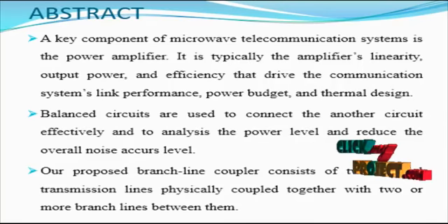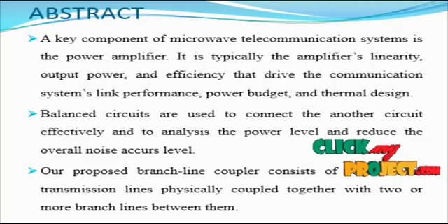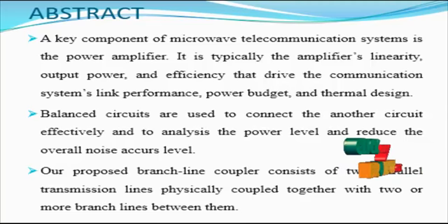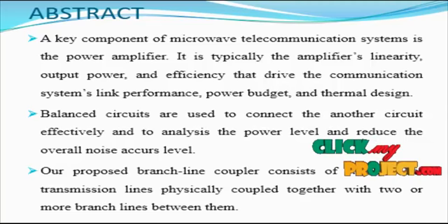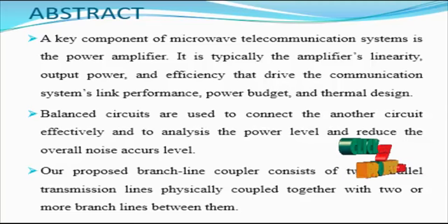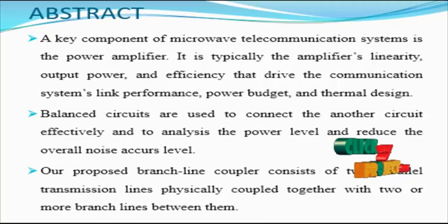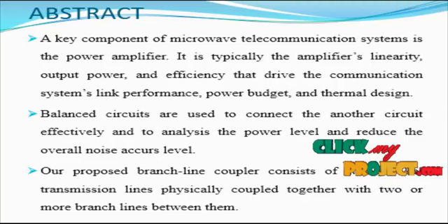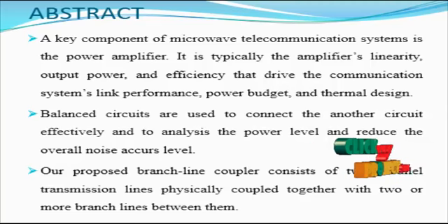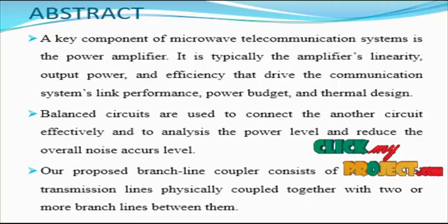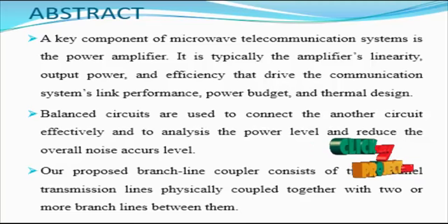Balanced circuits have been utilized more and more widely due to their higher immunity to conventional noise and easy connections with other balanced circuits. Many balanced circuits have been reported, such as the balanced diplexer. Like the balanced circuit, the balanced to unbalanced circuit also has the capability to suppress the common mode signal, but the latter can be connected with a single-ended unbalanced circuit at the same time, for example the balanced to unbalanced diplexer.